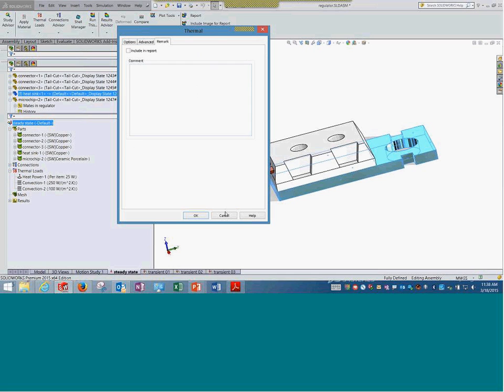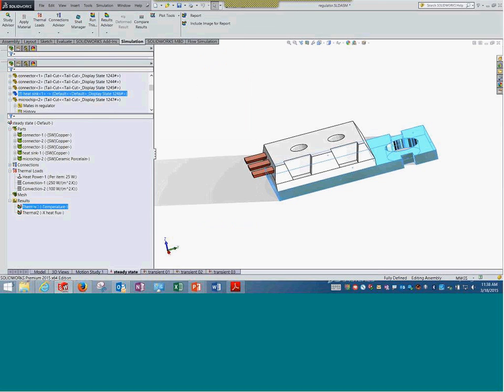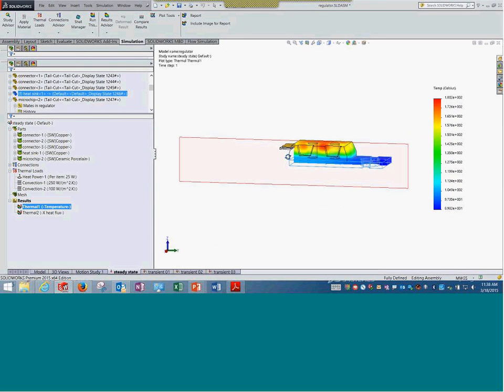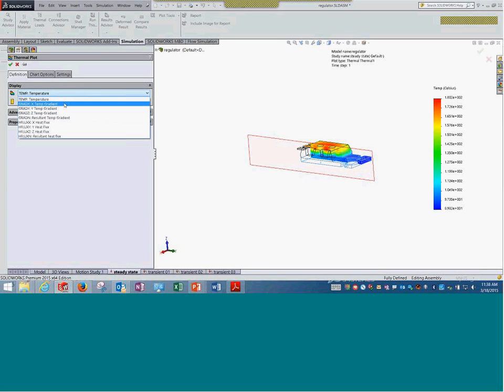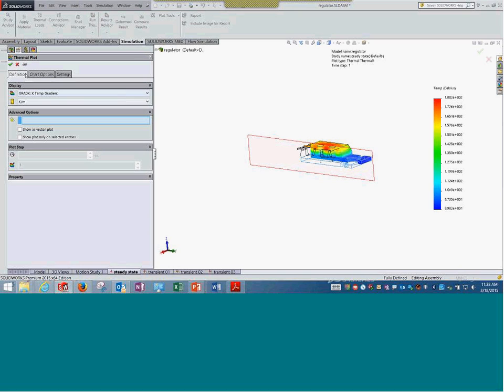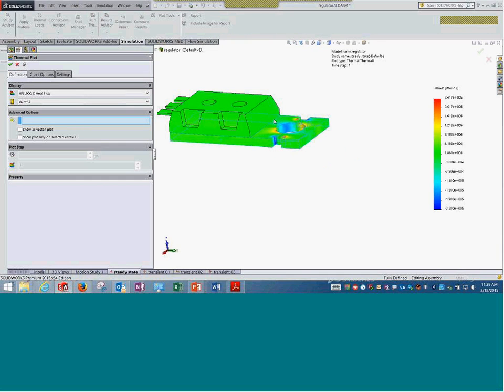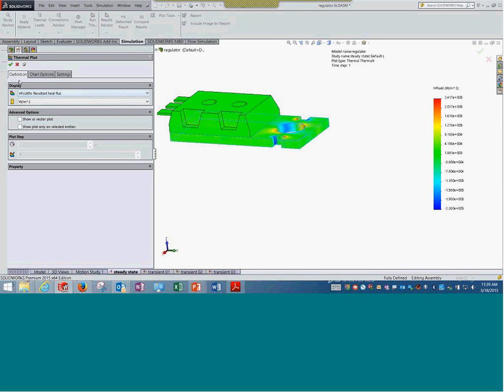On doing the analysis, typically we can see the temperature distribution, which is one of the most basic quantities, and the results could be seen in the body. In this direction, it is going to show you the temperature gradient. Frankly, it is difficult to interpret and may not have much significance. Most of the time we look at flux, which will tell you how much heat is actually going out of the system from what location, or how much heat is coming into the system. So flux is sometimes far more relevant than gradient, and we use it quite frequently.